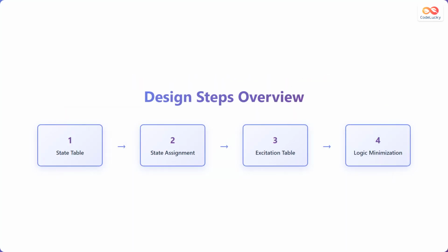To design a Modulo-N counter, we will follow these steps. First, we will create a state table. Then, we will perform state assignment. Next, we will construct an excitation table. Finally, we will minimize the logic to obtain the required circuit.